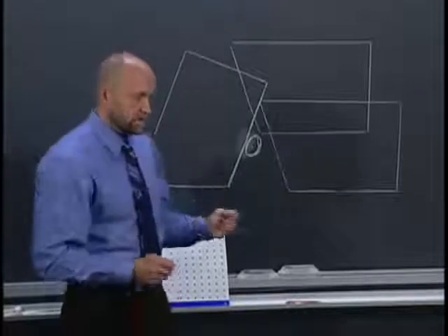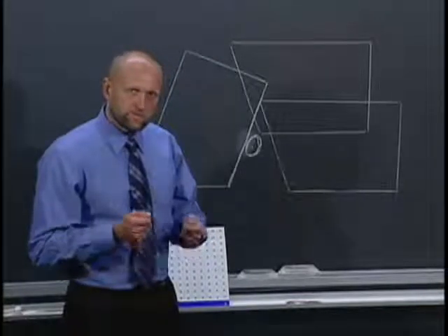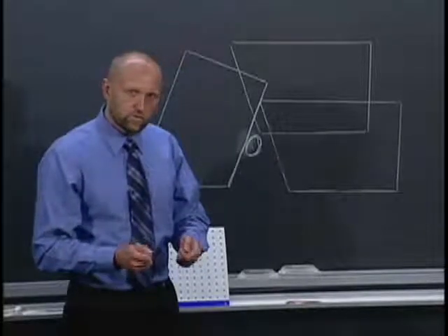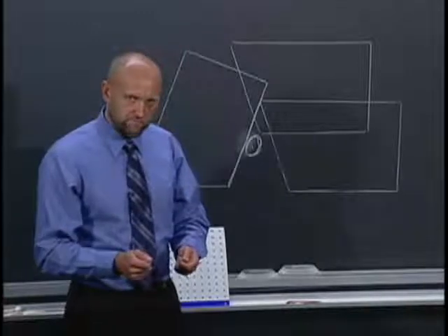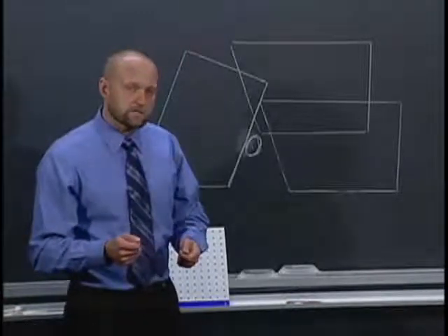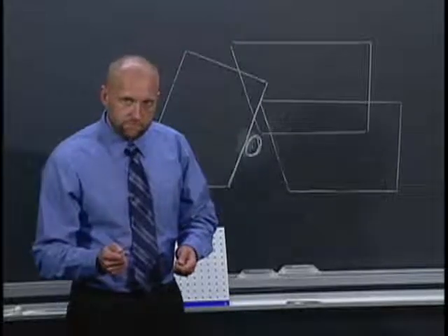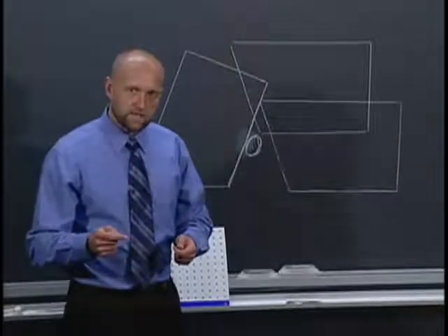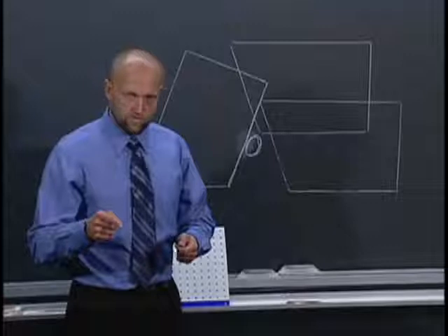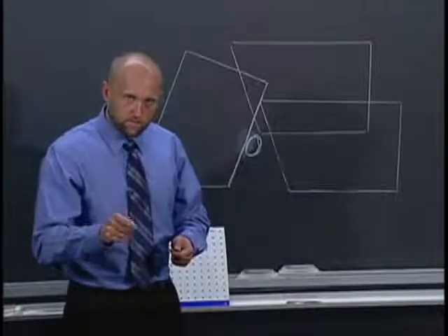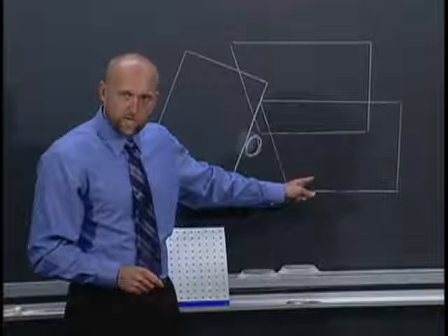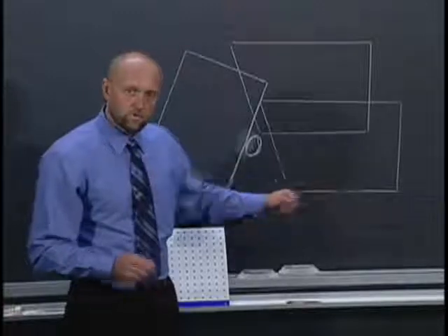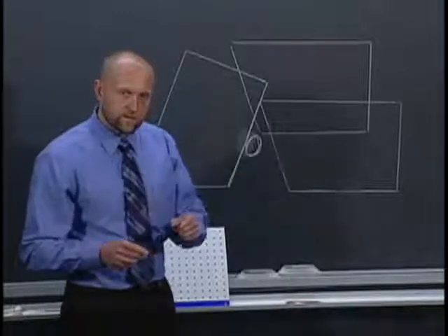So what we've done is define with some precision what we want the mechanism to do, the motions through which we want the mechanism to guide the bed. Now, if we want to guide this motion using a 4-bar mechanism, consider what we need to do. We know that a 4-bar mechanism has 2 links that connect from what we'll call the ground to something that moves. So the bed is that something that moves, and we want to figure out where the links on the ground go. So we have to come up with the locations of two joints at either end of that link.